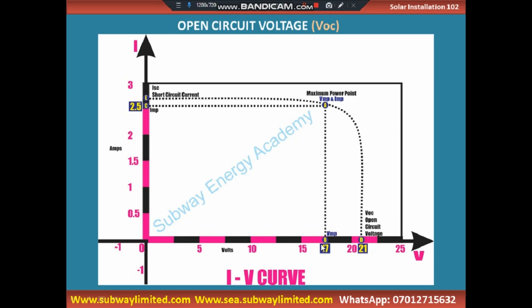So it is very important to test any solar module you want to buy in the market to be sure of the value of the open circuit voltage. Most times, desperate sellers might manipulate the solar nameplate. So if you go to the market with your multimeter, you will be sure of what you have when you are buying your solar panel.